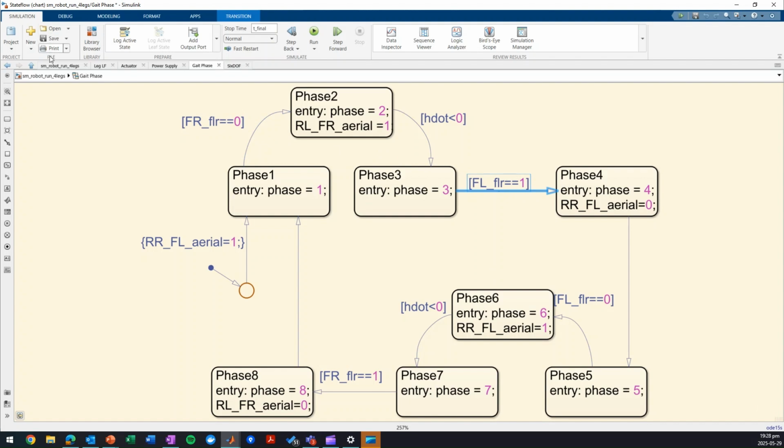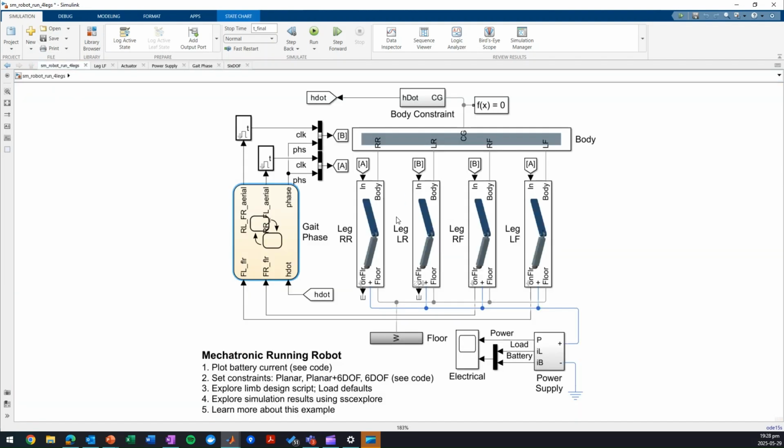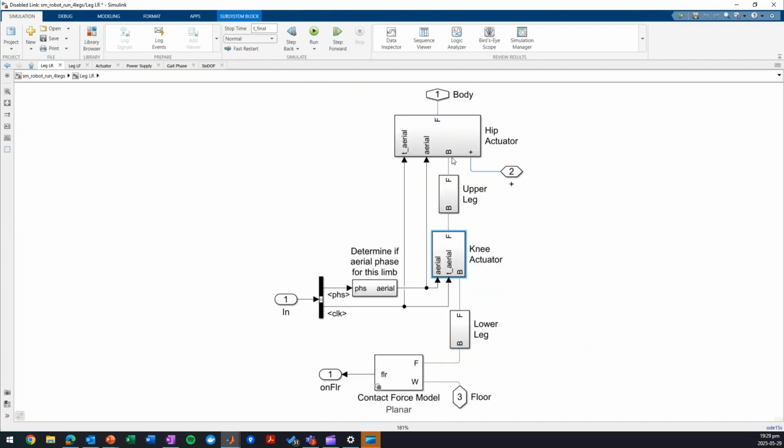It allows us to send specific instructions to the robot's leg subsystems, shown over here, during the aforementioned states. That allows us to activate Simulink and Simscape blocks in the knee and hip actuators situated over here, that output a torque to the knee and hips, allowing the robot to move its upper and lower legs, resembling a jogging dog.